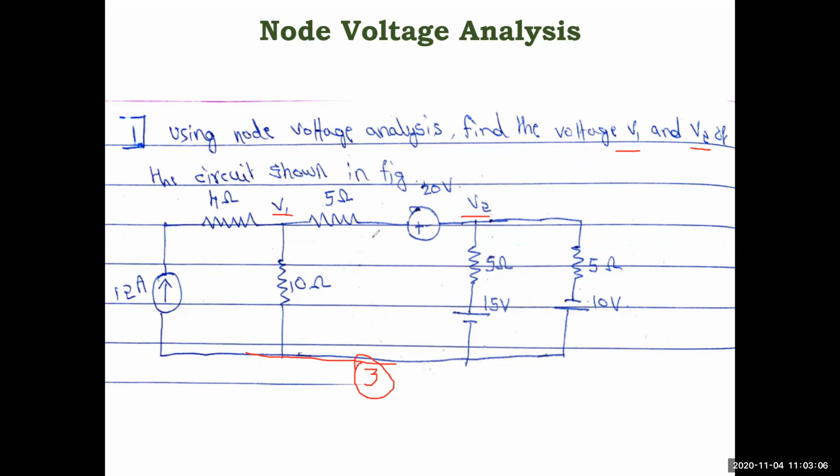Before we do the calculation, we have to make some changes. Whatever concepts we have learned, source shifting or elementary source transformation, we try to do here, because normally when we apply node analysis we are applying KCL straight away. If we have the current source present over there, then it will be better. Otherwise you may get confused, because every time you need to do the conversion.